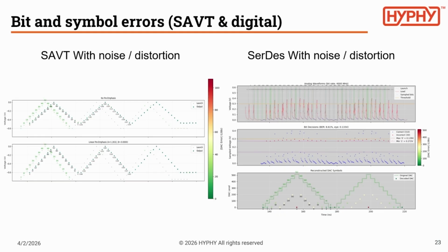There are a couple of things remarkable. So here is the direct input to output. There is the attenuation. It's a bit difficult to see, I'm sorry about that, but here's the input, and then because of the attenuation, this goes up a little bit. This is only the negative voltage part of the transmission. And so you see some attenuation, but after a linear correction, that attenuation is completely corrected, and we're pretty close, within 2 or 3 bits of the desired value. There's also a FIR filter corrected version of this, which is even closer to the output. I haven't got the data to show you here.